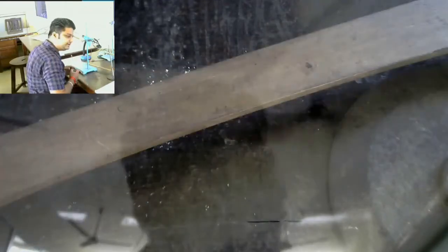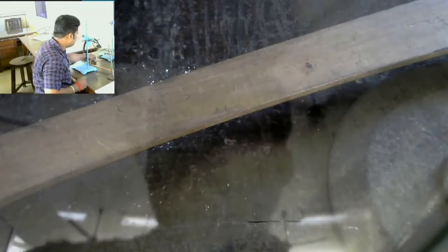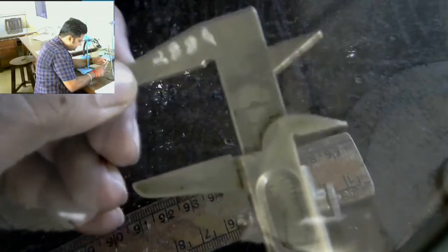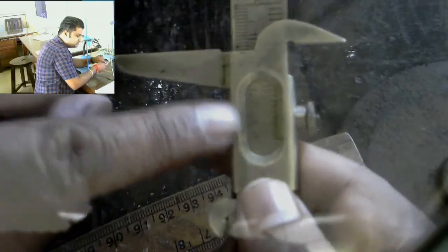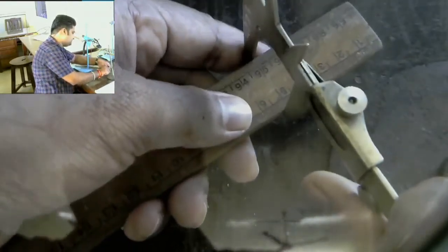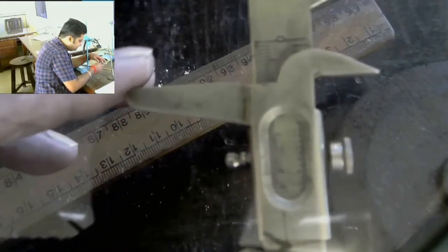Similarly, we will now use the vernier caliper to find the breadth of the scale. You can see the vernier caliper. The smallest reading on the main scale is 0.1, and the number of divisions on the vernier scale is 10. That will help you find the least count of this instrument. Again, let me take 3 different readings at almost similar points. I just take it out, and you can see it, I hope. It's not so clear, but good enough to see the reading.